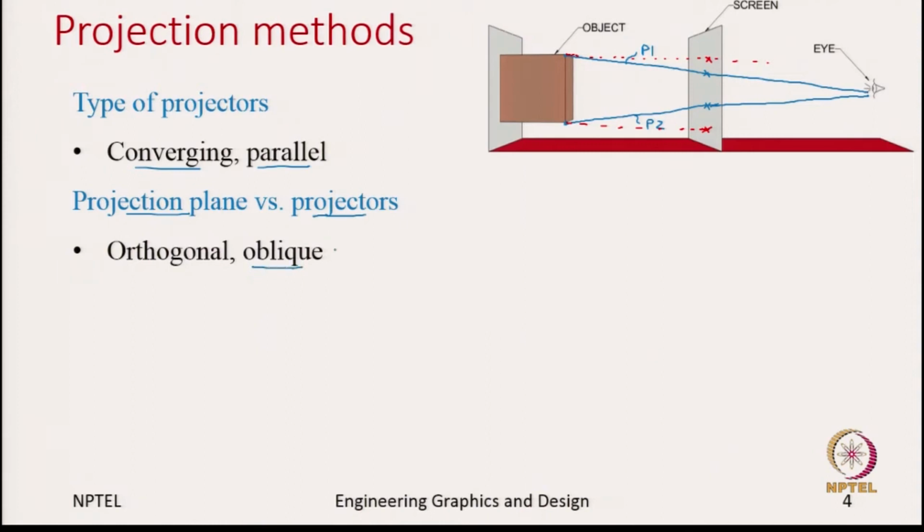projections. But in these red lines, let us say we look at the same thing in the top view, looking from the top. Now, what we see as the cube is a square, and this is your projection plane, which we will see as a line, and let us say we have an eye here, but very far, meaning that the observer is at infinity and the projection lines or the projectors are parallel.